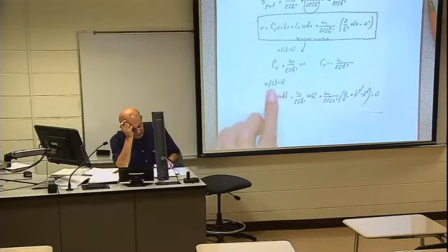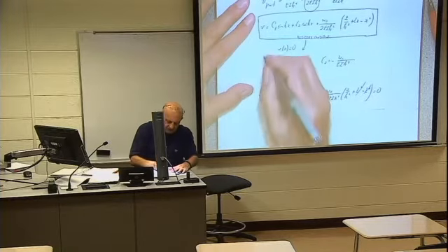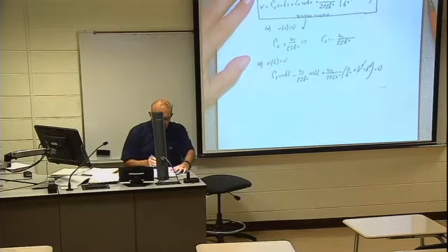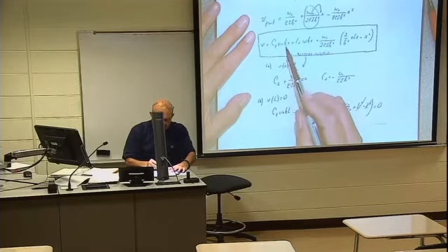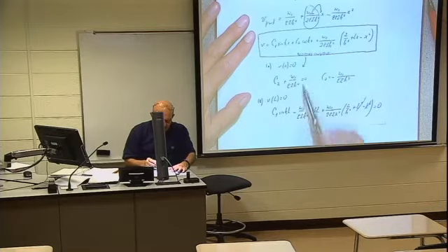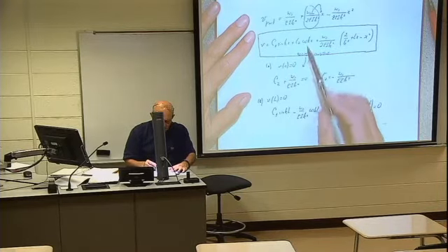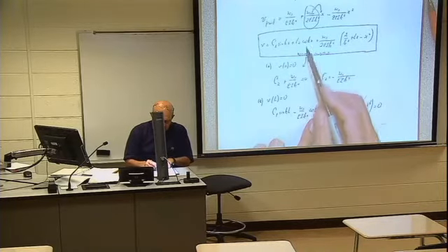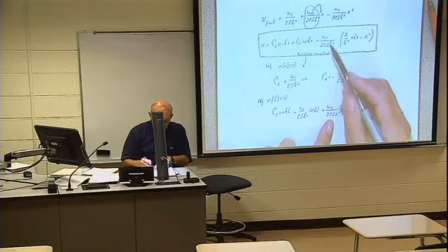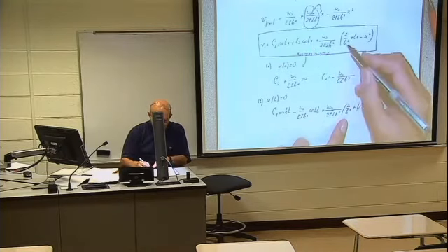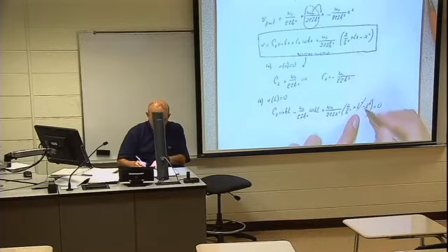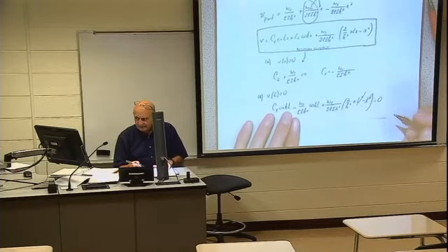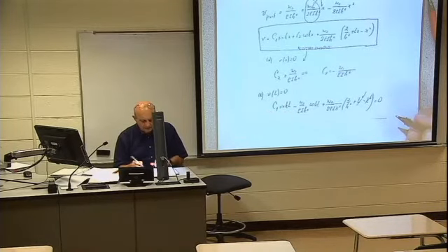Now V of L equals 0. That is the first boundary condition, and that is the second boundary condition. V at L, so then I substitute here. C1 sine KL minus, then C2 we found. C2 is minus W0 over EI k to the fourth power, cosine KL, plus W0 over 2EI k squared, 2 over k squared, L squared minus L squared. But L squared minus L squared is 0. This is 0.